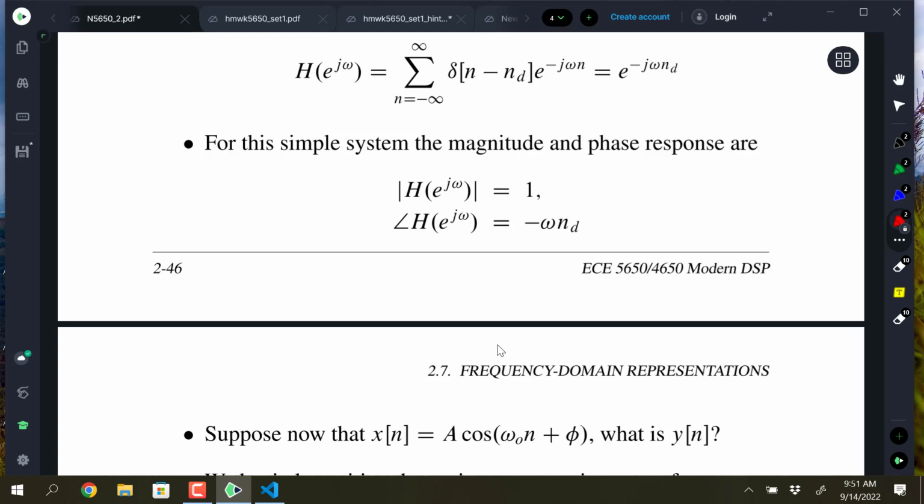If you look at what the frequency response is, it will be 1. If you want to model it more precisely with the source and terminating resistors, it obviously has an attenuation factor of 1/2, but that's just looking at the load and source, the fact that the load is 50 ohms, the source is 50, so half the source voltage is across the load, but that's sort of built into the model of the transmission line.